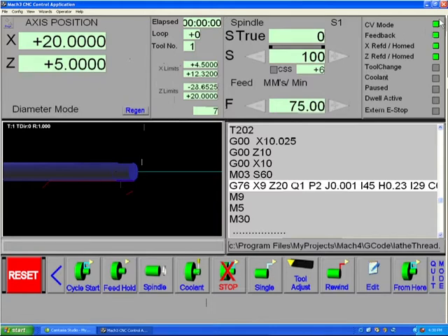We have indicator lights to show us if we're in constant velocity mode, something you normally are in turn, and whether or not feedback is enabled in the software. The feedback being enabled tells us that the software will be looking for a spindle index pulse, and will be using this spindle speed to control various things in the program, such as threading, synchronization, as well as constant surface speed. This DRO down here is the constant surface speed.